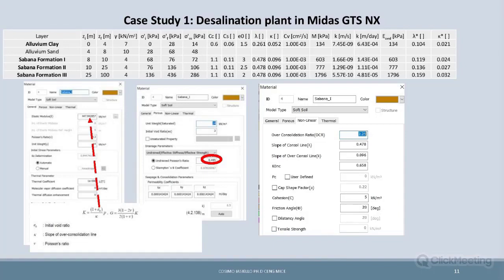First of all, we have some very good geotechnical investigation. We have an oedometer test, an in situ test, and an SPT. We have a lot of data, and we came up with this table, and we could implement this table in the soft soil model.